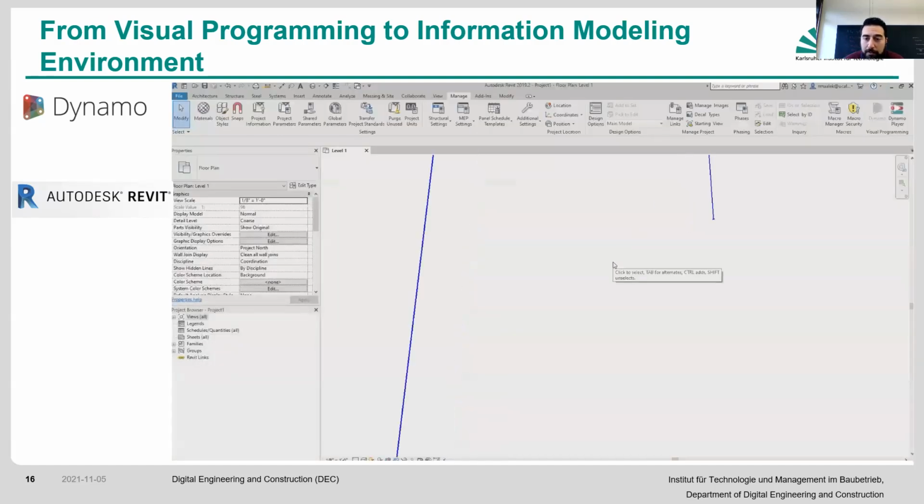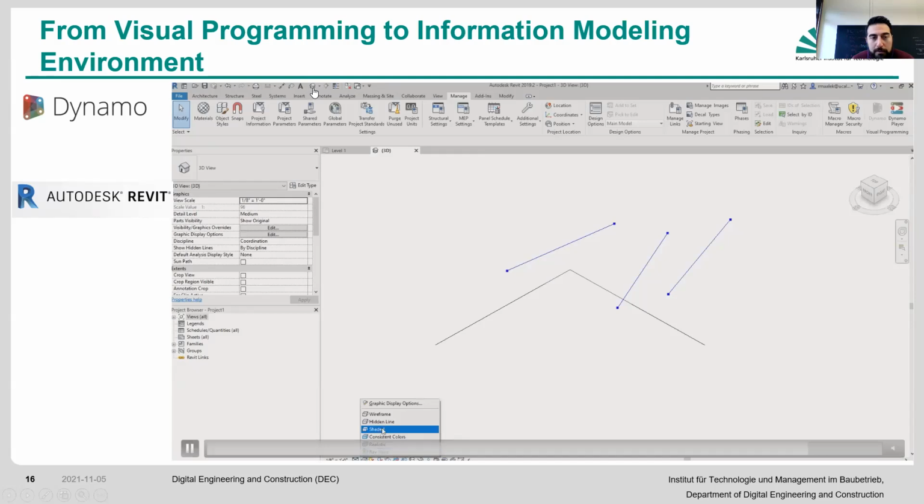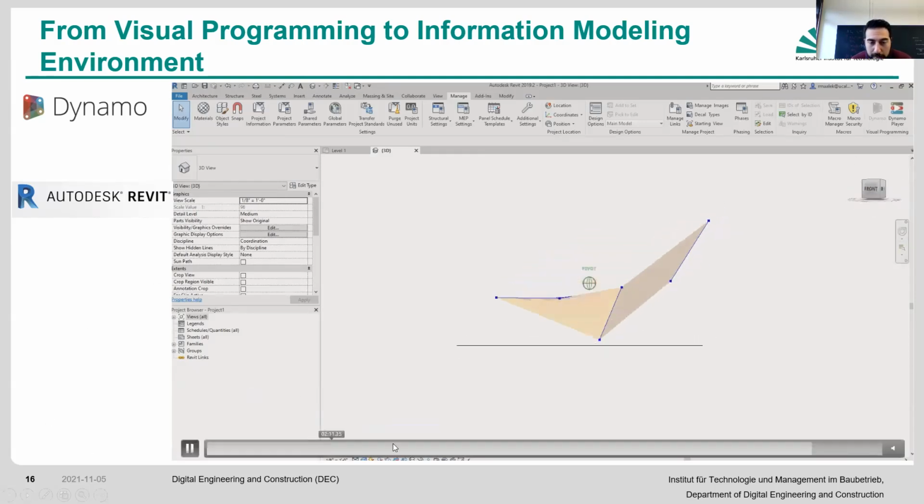Now, because you have that, automatically you essentially have this information. And once you go to the 3D view for your particular level, it might provide you with a better result. How you get to 3D in Revit is basically you click this cute house icon there. And once you go to the realistic view, it essentially shows you how it is.